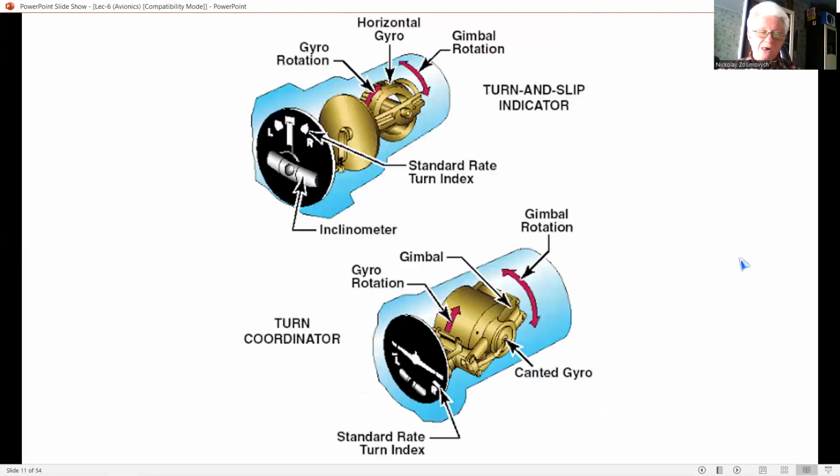In the case of an aerodynamically unstable aircraft, a well-designed proportional plus integral of pitch rate error control can provide an acceptable stable loop, though not an optimum one, without any other sensor terms, such as airstream incidence or normal acceleration.